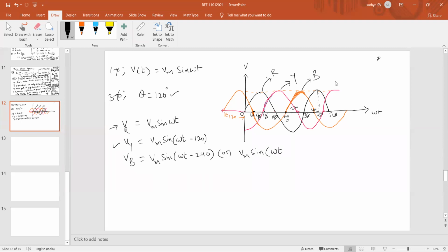See here, the B phase is also started earlier. This is the B phase, this color, right? Where I have extended to the negative axis. See, when you compare with the first one, the first instant of B phase is started in a negative manner, right? Negative in the sense, lead or lag? Lags. See, negative in the case of the sinusoidal representation.